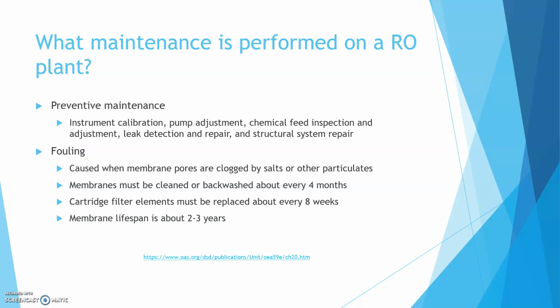What maintenance is performed on an RO plant? Preventive maintenance. What is preventive maintenance? Instrument calibration, pump adjustment, chemical feed inspection and adjustment, leak detection and repair, and structural system repairs.